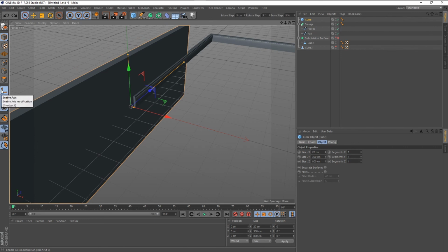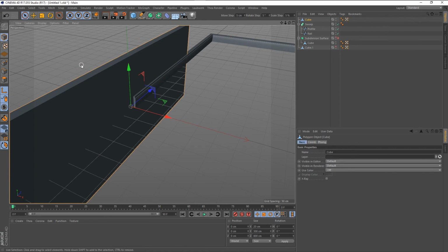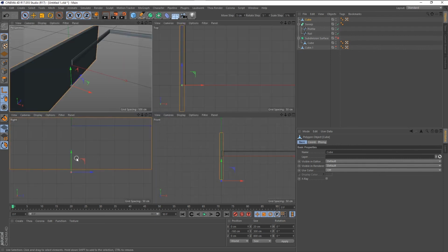So if you're trying to change the axis and it won't let you do it, first you have to make it editable. So click that button or hit C. And now I've made it editable, so I can enable the axis and I can move that axis down. And if I go into my front mode, it should, oh, Shift S to snap, so enable snaps, and now it's snapping to the edge. Now I have, go back, turn that moving axis,